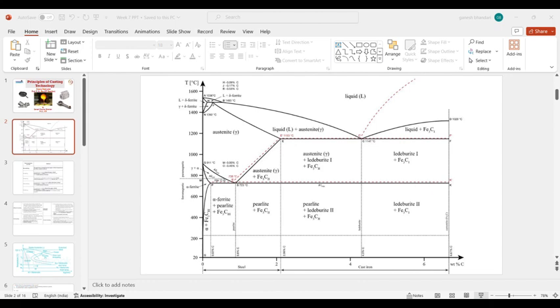Okay, because in any heat treatment process, what we are doing, we are refining the grain size of the sample. When we talked about the solidification process, we had already talked about the grain size, what types of grains are going to form there. It can be dendritic formation or it can be equiaxed grain according to your solidification process.